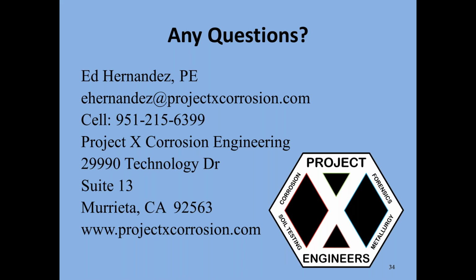So the only challenge is that if you're laying gas lines or pipelines, and you're required to put cathodic protection onto those types of pipelines, electrical currents don't travel through rock very well, if at all. So that's the challenge. Now they have to figure out a different way of cathodically protecting that pipeline. But in general, no, very low corrosivity environment if you install things in rock. Okay.